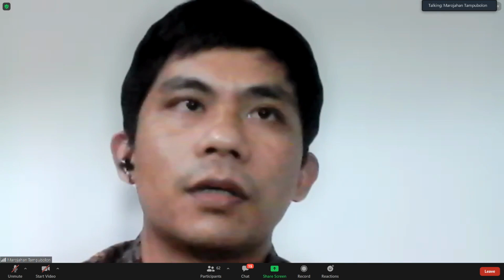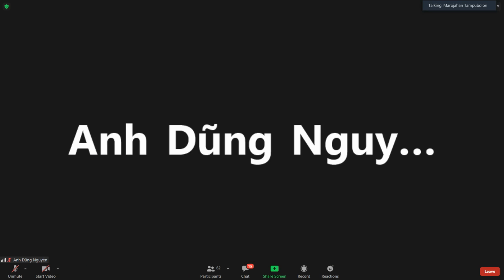Right now, the common frequency for inductive power transfer is about 81 to 89 kilohertz. That's a common frequency, and as I know, that's also the slot that is not occupied by other technology. So that's why most researchers use this frequency.